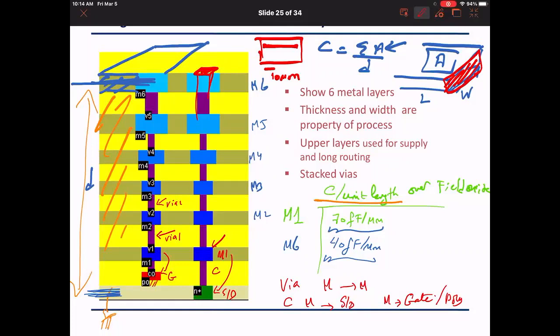In the top layers we do routing for the clock and then it goes down, and even the big supply goes from metal 6 down to the lower metal layers. But typically the lower layers, where you have the activity of charge and discharge, is where you get most heating. And it is most dense, they are closer to each other and the resistors are smaller. Okay, but it depends on the design of the chip. Okay, thank you.